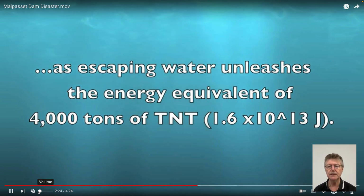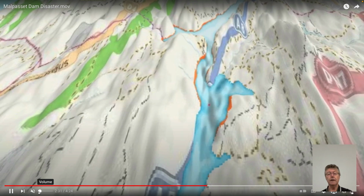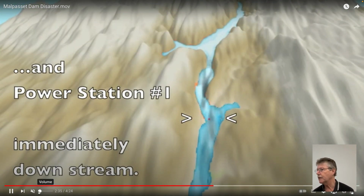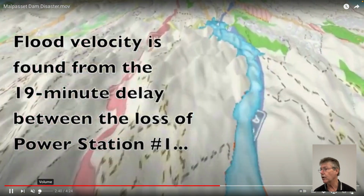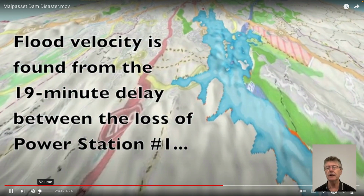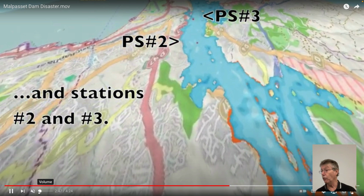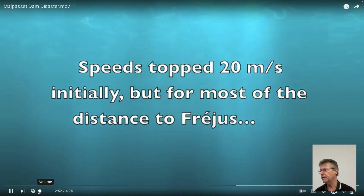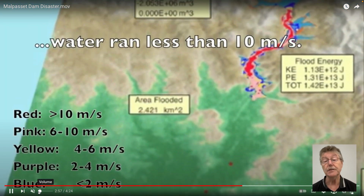And there was another disaster in the Alps shortly after that, the Vajont disaster, that was also an arch dam that failed. And so, public good, engineers, you design for what you know at the time. Perhaps things weren't known so well. The failure wasn't in the dam concrete itself, which was plenty strong enough to resist what was going on. The problem was the abutments shifted because there were faults, joints and fractures in the abutments. It moved. The dam is quite brittle. When it moves, it fractures, and as a result, the water flooded downstream.